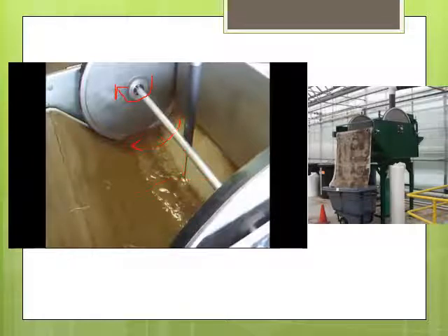So these are very popular primary filters. And you can see here the water is cascading down. The waste paper is actually going directly into a bin, and when the bin is full, they cut it off, roll it out to a dumpster, and throw it away. And it's just biodegradable paper. It's not a big deal. And it's very clean and effective at removing large debris. Here you can see there's another roll ready to go.